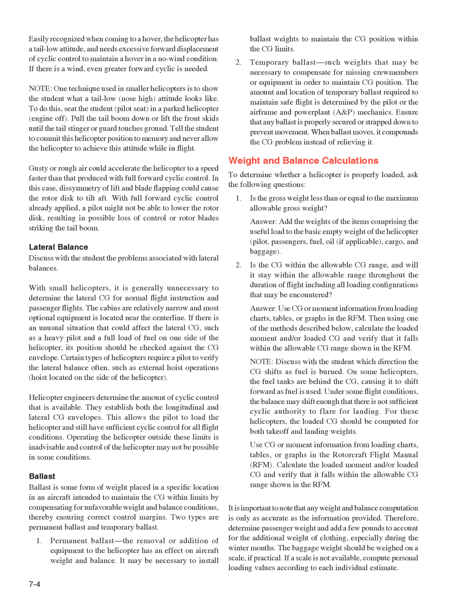1. Is the gross weight less than or equal to the maximum allowable gross weight? Answer. Add the weights of the items comprising the useful load to the basic empty weight of the helicopter: pilot, passengers, fuel, oil, if applicable, cargo, and baggage.